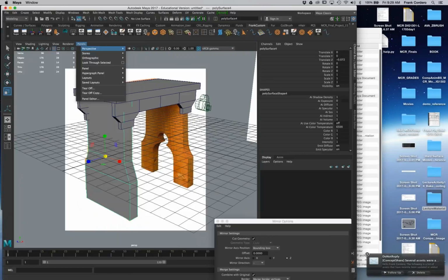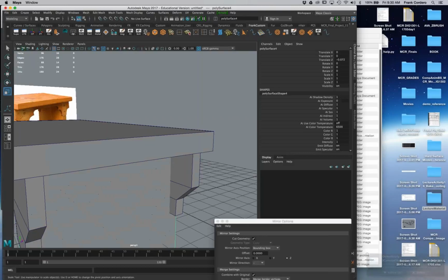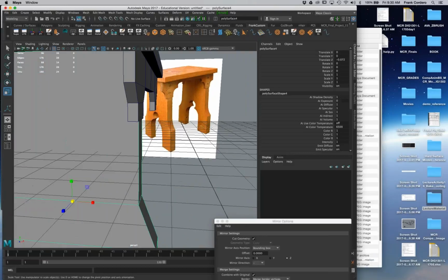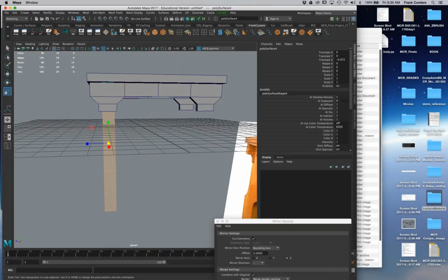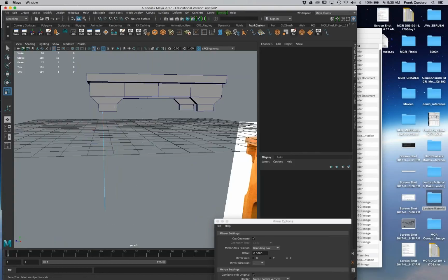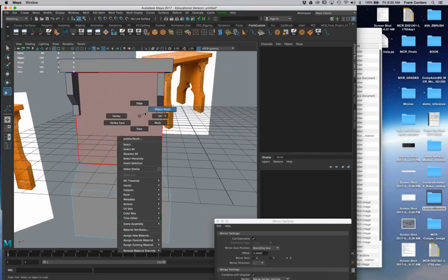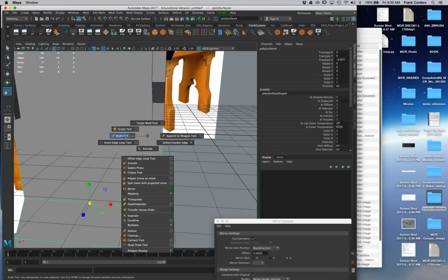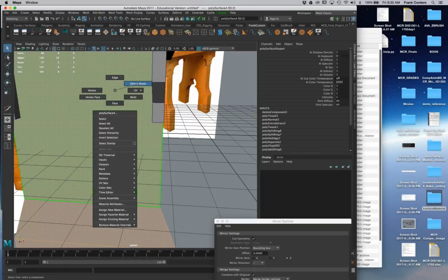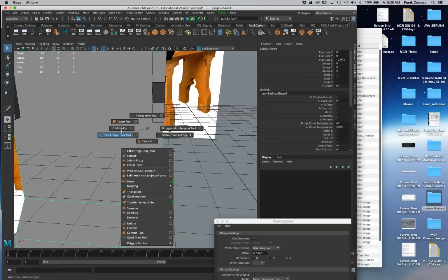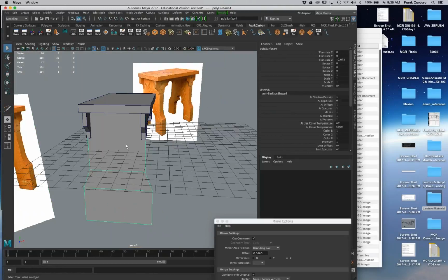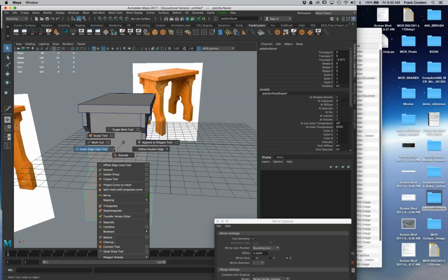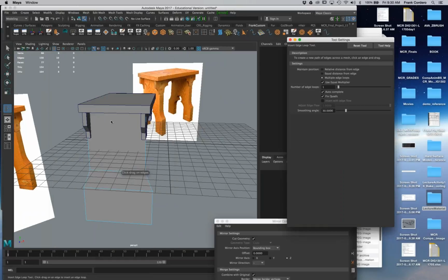All right. So what I might do here, guys, is go back to the model. While this is flat, and this is one of the reasons why I go back to making this flat geometry, I'm going to get rid of all this stuff. Boom. And then in the easiest state of modeling, I'll go with my multi-cut tool, or I can just do this. This actually might be even easier. You know what? Screw it. Let's go multi-cut. But before we do multi-cut, I'm going to split this in half. I'm going to make my life easier because this is all about thinking a few steps ahead. I know I'm going to mirror this at some point, so let's just split this in half.